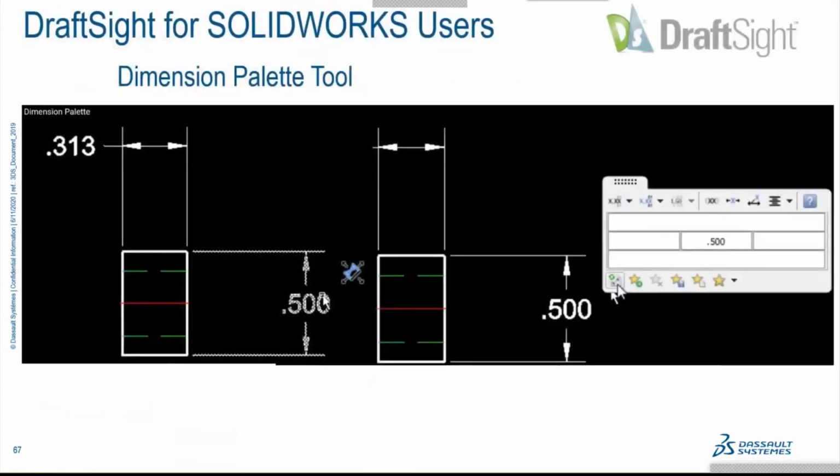We also get the dimension tool palette. So everybody knows this little button that you have here. And if you're a SolidWorks user, I click this dimension, this little box comes up. If I move my mouse over this box, this will fly this out, and I can enter text before the 0.500. I can enter it after. I can enter it above. I can enter it below.